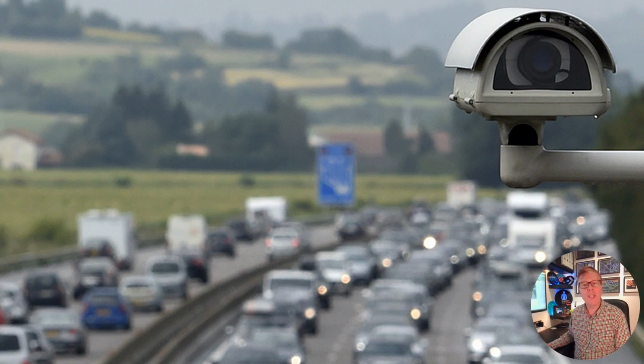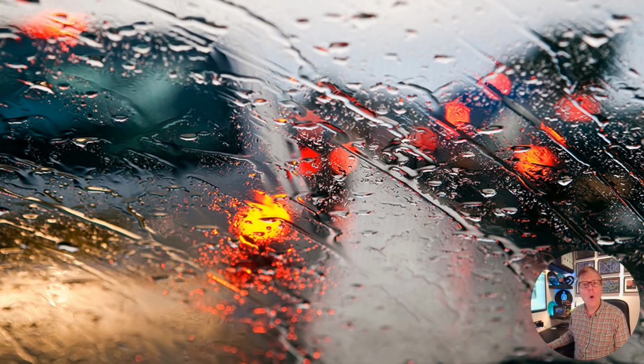Video sources have been used extensively for detecting vehicles for a long time. Originally, this type of technology looked for changes in the appearance of pixels within a predefined detection zone in order to signify the presence of a vehicle in that location. Although this gave a good proxy for vehicle presence, it suffered from reliability issues prompted by a range of factors, ranging from false triggers caused by shadows cast by passing vehicles to an inability to see objects reliably at night or because of harsh climatic conditions such as heavy rain, fog, or snow.